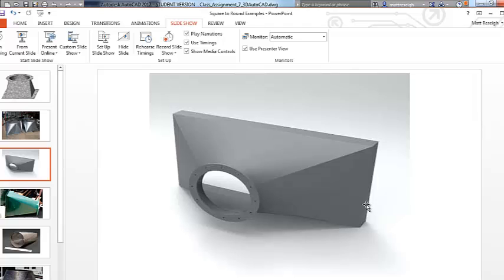Because of whatever the purpose of it is, it needed to be an offset taper. We're going to look at an equal taper square and an equal taper rectangular. And then as this went on, in the next series of lessons, we would look at pushing one of these to offset to an unequal taper. And this one shows a collar section also, where we're going to the flange here, where the pan and the squared round stops. We've got a short section of collar to transition to round.